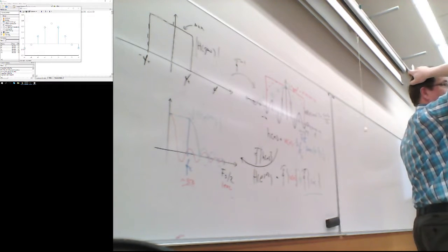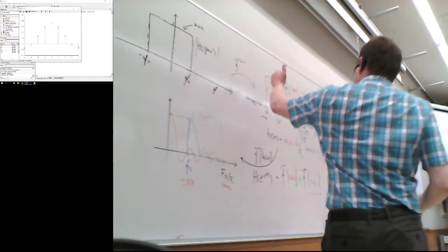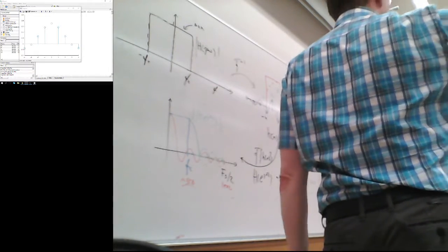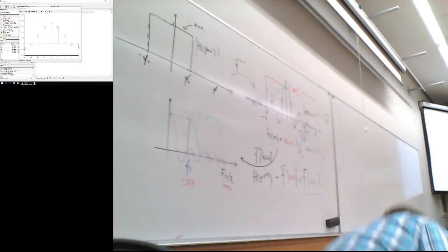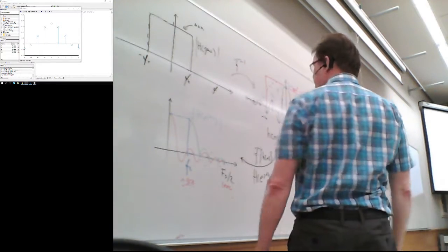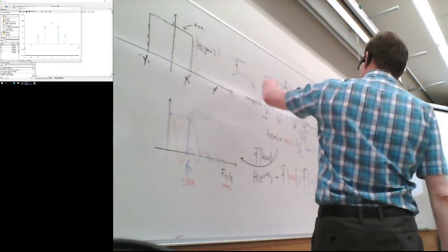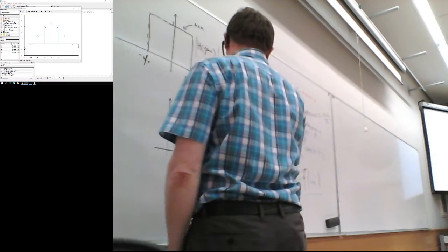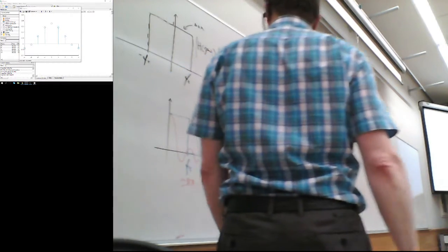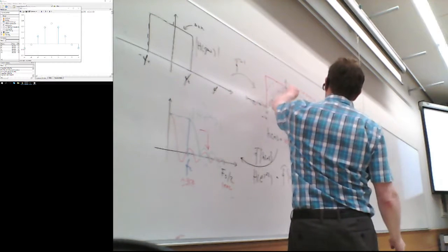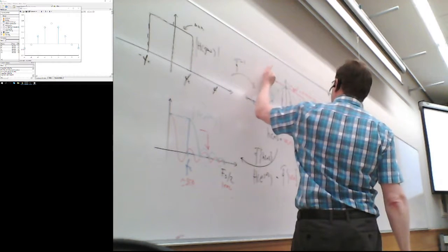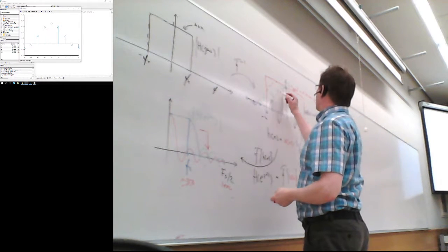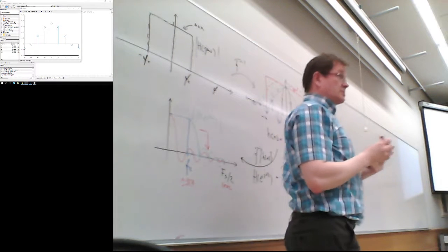Anyways, on the 7th harmonic you still have quite a lot of energy. So basically the only way to start getting better attenuation in the stop band is to smooth the window somehow. Get rid of these sharp edges. And one way of getting rid of the sharp edge is the triangular window, which is very simple to produce.